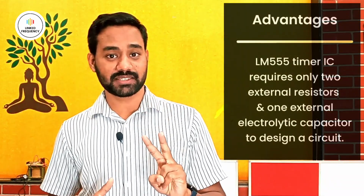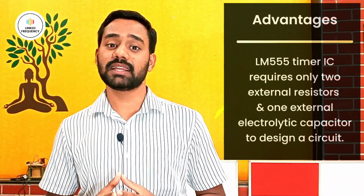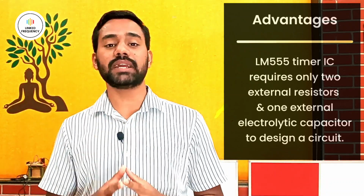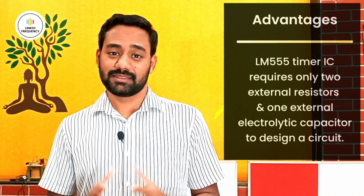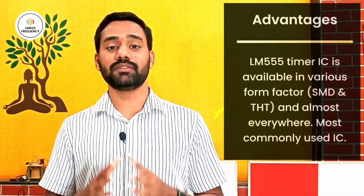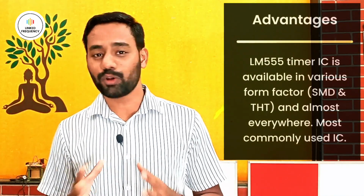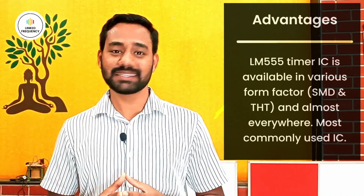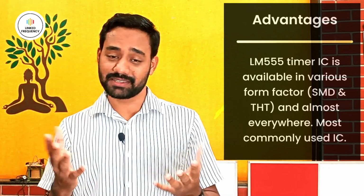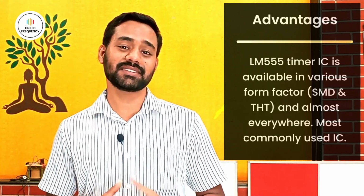Third advantage is it requires only 2 external resistors and 1 external electrolytic capacitor to tune its pulse width and pulse duration. That's how easy it is. That's why it is more popular in industry. Fourth advantage is this IC is available in various form factors and almost everywhere. If you go to a local shop and ask for a 555 timer IC, you will get it. That's why it is very advantageous for design engineers to consider it for their design activity.